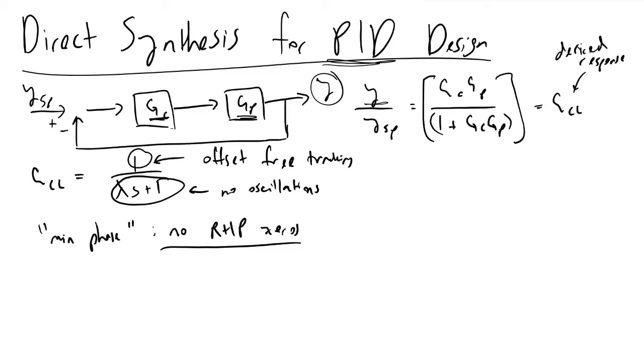block. And so we're going to be assuming in this example that GP, our process, which is a physical characteristic of our system that we have no control over, has no numerator dynamics, and we don't have to take that into account, and it is also a first order system. And so now that we've done that, I'll go through how we can determine what our tuning parameters for our PI or PID controller should be on this first order process.